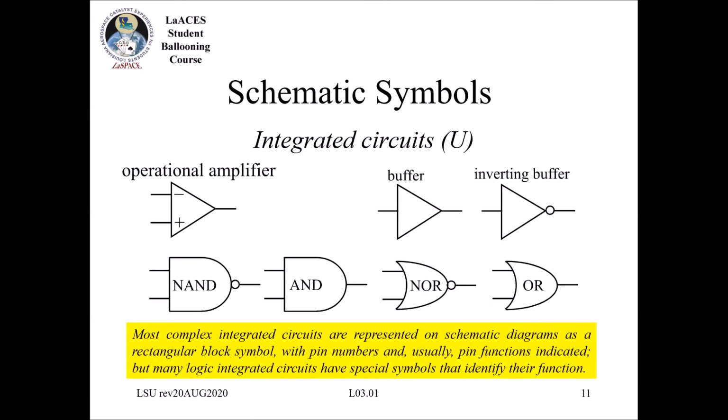The operational amplifiers, these are integrated circuits, you start to see that. You see the operational amplifier, you'll see a minus and plus. Sometimes there's also a version of the op amp that's just what we call a buffer. The signal follows. Whatever you put in basically is out, but oftentimes there's a change in impedance, which might matter to a microcontroller. It's really important to think about that and understand how whatever the smart thing is that's looking at it, it might want to see a very low impedance or resistance. Impedance is another way to describe resistance, so if you hear me say that, that's what I mean.